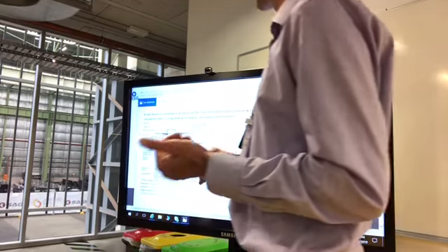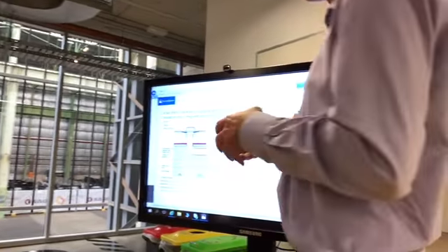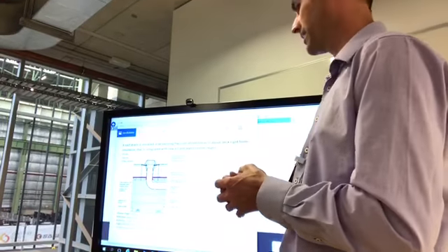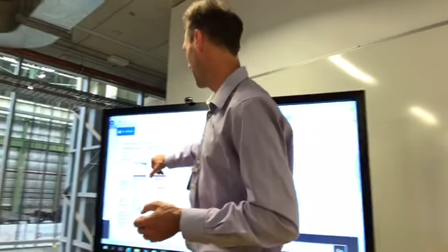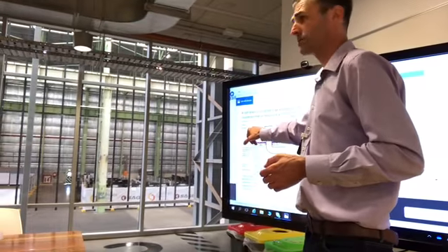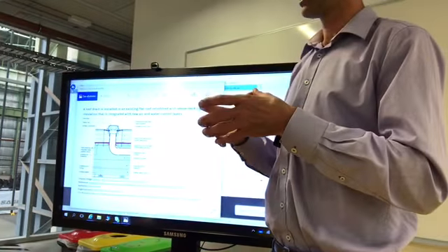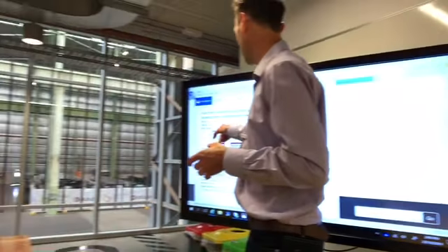The important point is to understand that we've got these small drains hooked up with that drainage pipework, and typically, in Australia, it's going to be an EPDM membrane that folds down under those drains, and so we get sealing under that. Would we have any concrete or anything over the top of that? No, so no concrete goes over the top of it. So that's the top roof surface there.